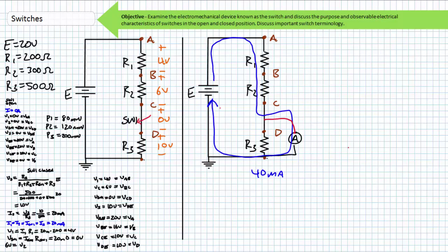Long story short, if current is too high, it's because resistance is too low. Either you're using the wrong components, you're building the wrong circuit, or you're shorting out components with a low resistance path, be it an errant wire, incorrect placement of a switch, incorrect use of an ammeter, or incorrect placement in the protoboard. Shorted components cause current to rise.